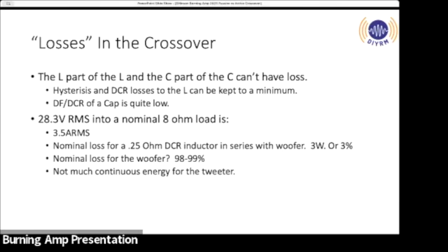And when I say feedback, I mean that system went rails and they couldn't get to the gain controls in time. And usually what burns out is the L pad on the tweeter, right? Or the capacitor on the tweeter. Those are smoked, right? I've seen some comically undersized inductors blown up, but I don't think I've ever seen a properly sized, real inductor blown up. All right.